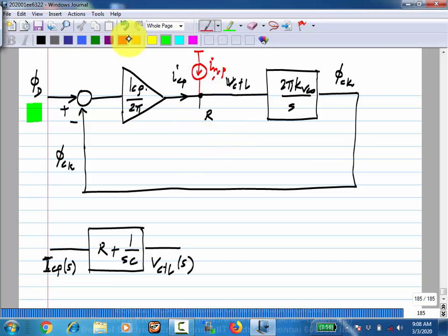In this case, a series voltage source may be more convenient. So you'll have the noise voltage of the resistor. And then we have not looked at the model of this, but the VCO again will not give you a perfectly periodic output, even if the input is constant. It will have its own noise. So its phase noise has to be added.